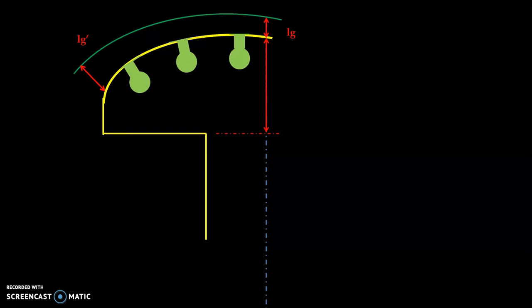We have height of the pole shoes. Height of the pole shoes, in case when we use the damper bars, is important. So HL, that is the height of the pole shoes. Then we provide the saliency and the height, that is HG. And ultimately, diameter of the damper bar. Here we can see the diameter of the damper bars.